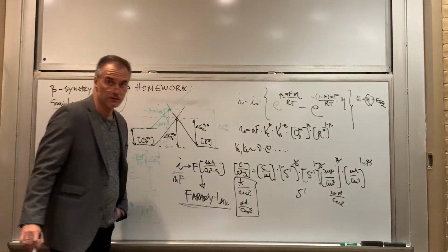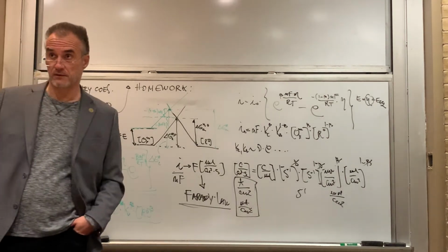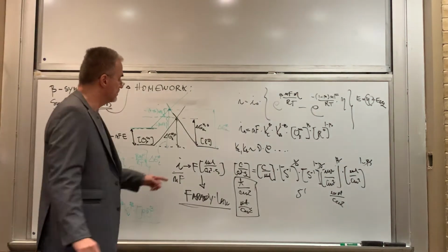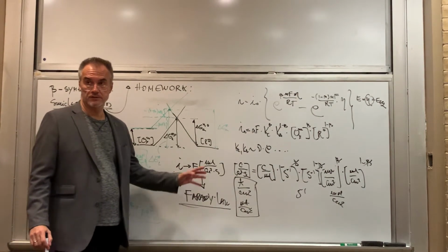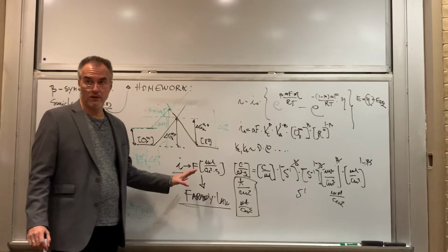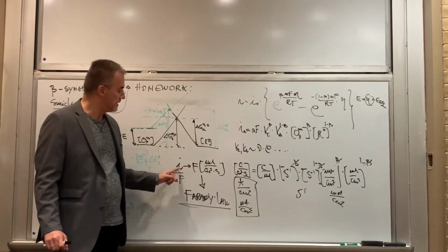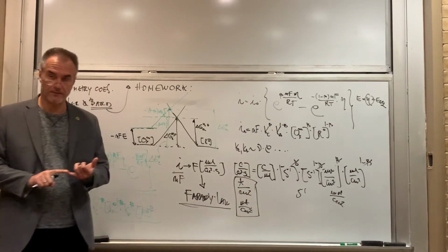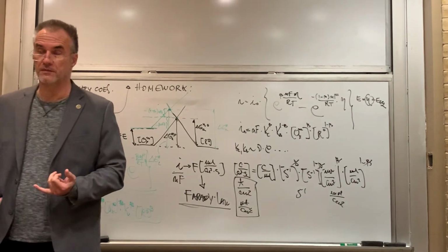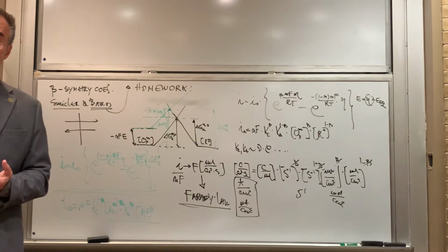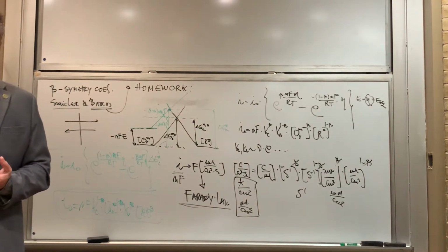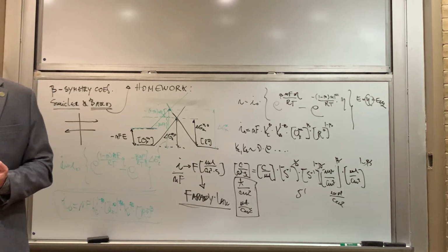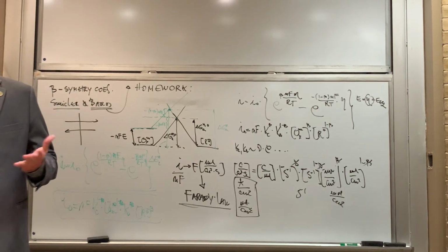And I'm not going to teach Faraday's law because it's trivial, but the convenient thing for you guys is to play with different expressions of this flux or current density by multiplying with a certain constant to get an expression for the rate in nanometers per second, for example, or get the expression for mass flow in kilograms per second, etc. Right?